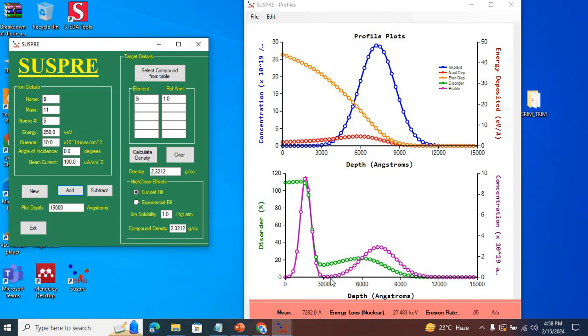So up to approximately 300 nanometers of the host material, we will have n-type doping, and then from 0.3 to 1.2 micrometers, we will have p-type doping of the substrate. We can also make a p-n junction out of this.